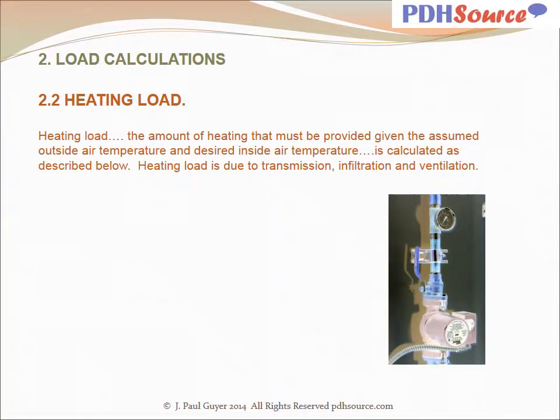First, with regard to heating load. Heating load is the amount of heating that must be provided given the assumed outside air temperature and the desired inside air temperature. It's calculated as described below, and heating load is due to transmission, infiltration, and ventilation.